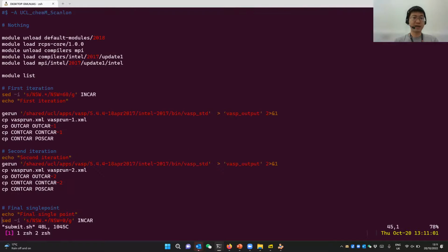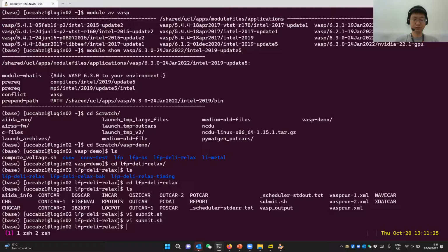By restart, what I meant is you have to write multiple lines that launch VASP. You can't just write a single line, run VASP, and then expect your structure is fully relaxed and energies are consistent. Especially for variable cell relaxation. If you're not changing the cell, you can just do a single calculation, and that would give you the energy that is consistent. So that's basically this example.